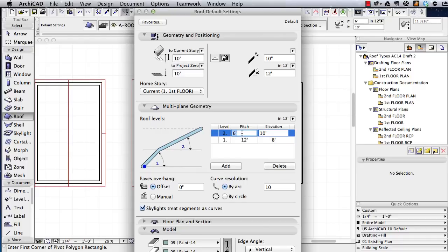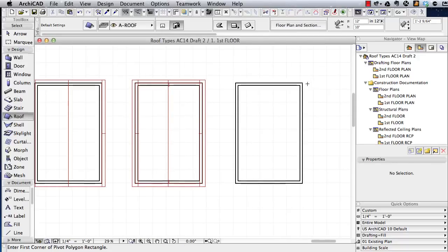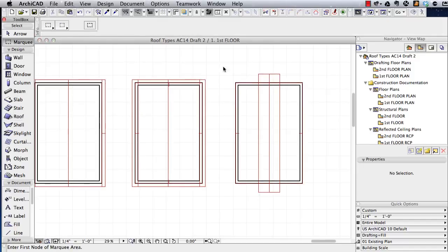Then I'll have a different slope. I can't type in a negative value. If I type in -12 or something like that, it will just constrain this to something that's very close to 0 but not 0. It won't go negative. So I'll just put in some arbitrary value here, and I'll adjust that afterward. So I'll say OK, and we'll create this shape. And you see that we actually have a rather odd situation here. Let's take a look in 3D, and we'll correct these things.